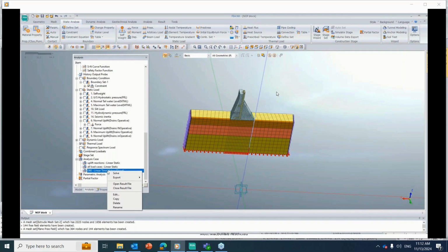Okay, so we can plot a curve between time period and the acceleration of that structure based on the damping properties of that. That curve is called the response spectrum curve, the acceleration response of that structure versus the time period. So in the early 20th century, people knew that this is there, and people had recorded the accelerations of the ground motion also. That also seismologists know.